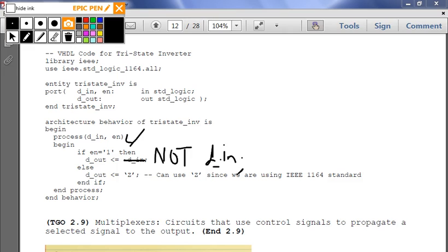So you have these problems that you kind of see that the problems are a little redundant. If I wanted to create a tri-state buffer and I had this code, what would I want to do? Yeah, just get rid of the not and change it to tri-state_buff. And then use a different VHDL file, run the simulation, and you're done.